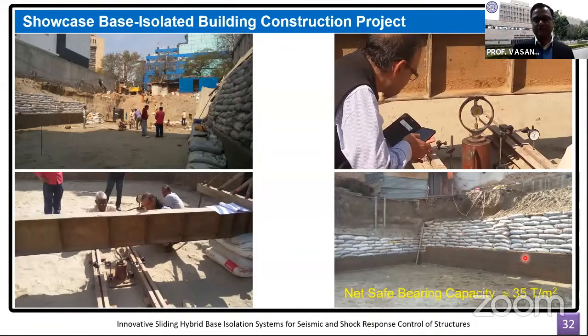You can see that there is a lot of loose clay soil surrounding this, and this is clay sandy soil typically observed in the Trans Yamuna region. Therefore, because of the poor quality of the soil here, some treatment was given at the foundation level, and micropiling was done. Please note that this is not invariably required for any project. It is particular requirement of this site where the soil conditions were poor.